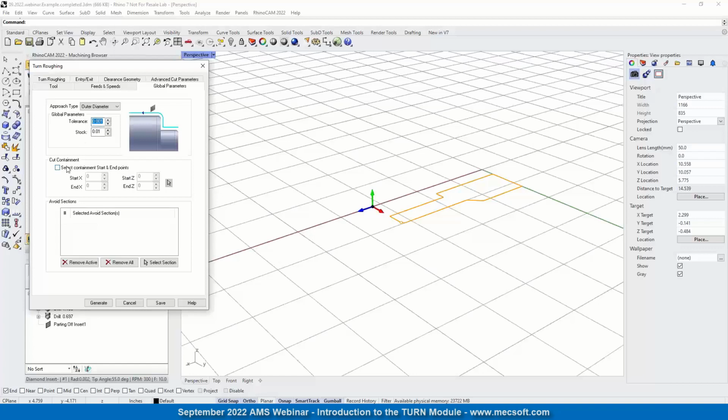We've got a tolerance that we have set for roughing. This doesn't necessarily have to be really tight. It defaults to 0.001, we'll just leave it there. We're going to leave 10 thousandths of stock on the outside. Again, if I'm going too fast, ask questions so that we can get them answered, and let me know and I can slow down a little bit.